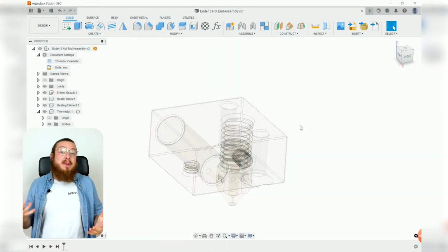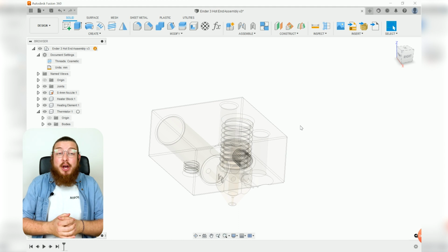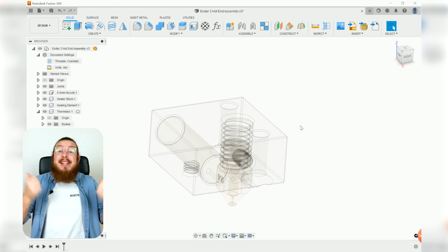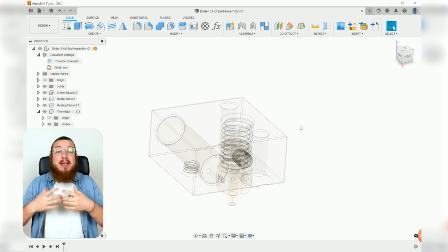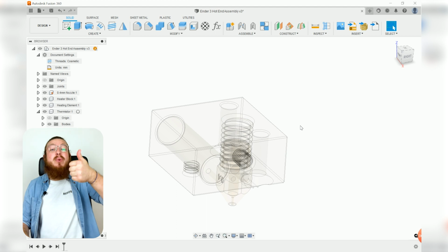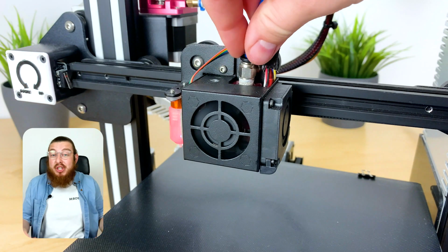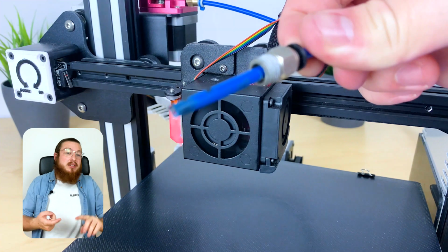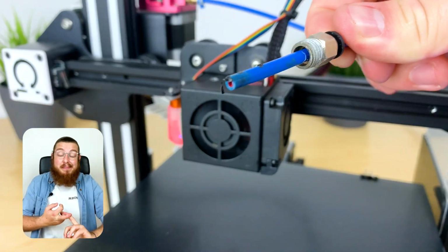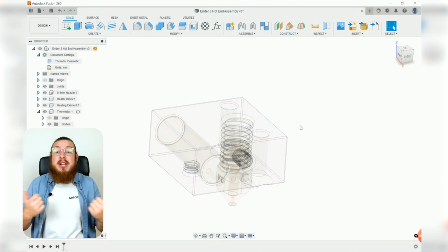So as a very fundamental truth in 3D printing, yeah, we want a lot of heat to melt our plastic, but as soon as it's done, we need to get that heat out of there as fast as possible because we don't want to form heat creep, where the thermal energy is working its way up everything and starting to melt plastic higher up than it really should. This can cause clogs, and this will degrade all of the PTFE tube very, very quickly. And so we want to be able to get rid of as much heat as possible.